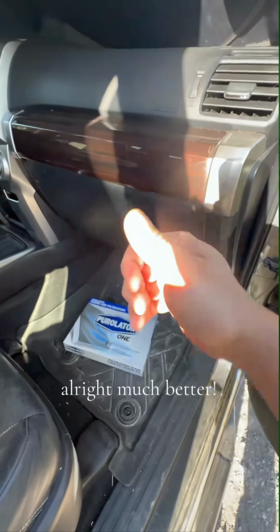This one's going to take a lot of cleaning. Looks like it's old grease mixed with rust and dirt. I'm going to use the scrubby side of the towel to knock off that buildup. And there was no excessive wear on the caliper pins, so I could reuse them. And surprisingly, the brake pads and rotor were okay also. And I also made sure to clean up the caliper where this pin goes in. These pins are supposed to be nice and lubricated, that way the brake caliper can move freely. If not, the brakes won't work properly, which can lead to uneven brake pad wear, or like we had on this car, brake noises.